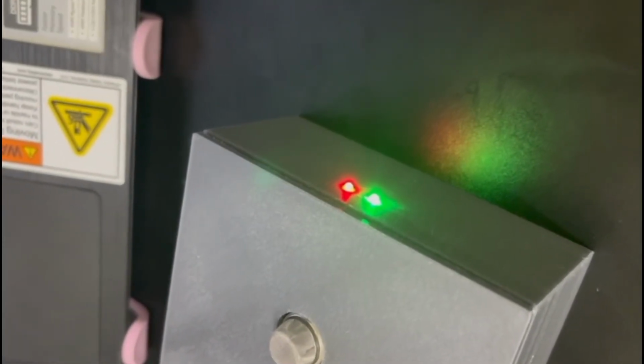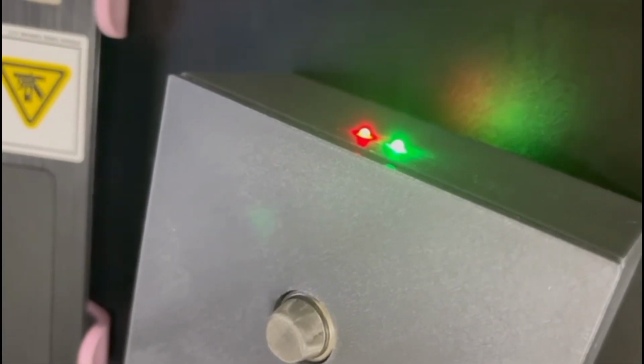When the gas sensor detects moderate quality, the two LEDs turn on, red and green at the same time, so the status is moderate. The gas reading for moderate is around 200 to 400, and the gas reading right now is 318, the temperature is 28.90 Celsius, and the humidity is 68%.